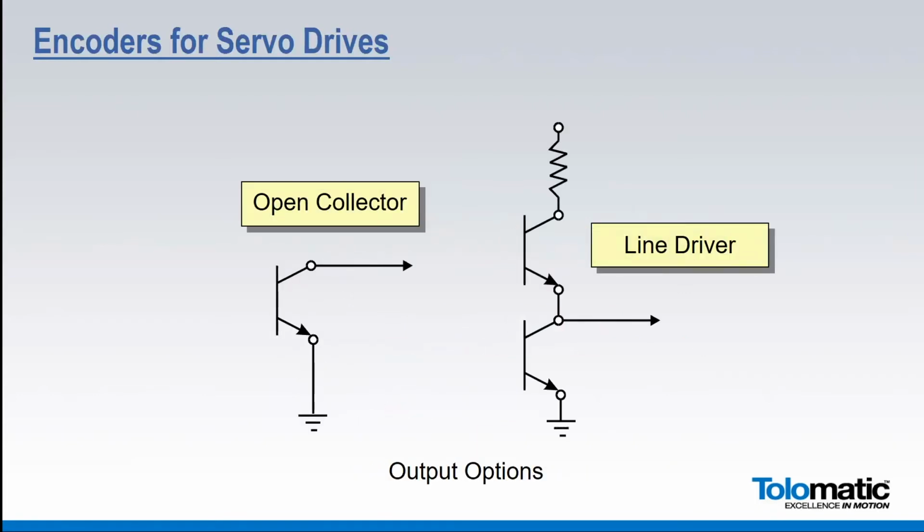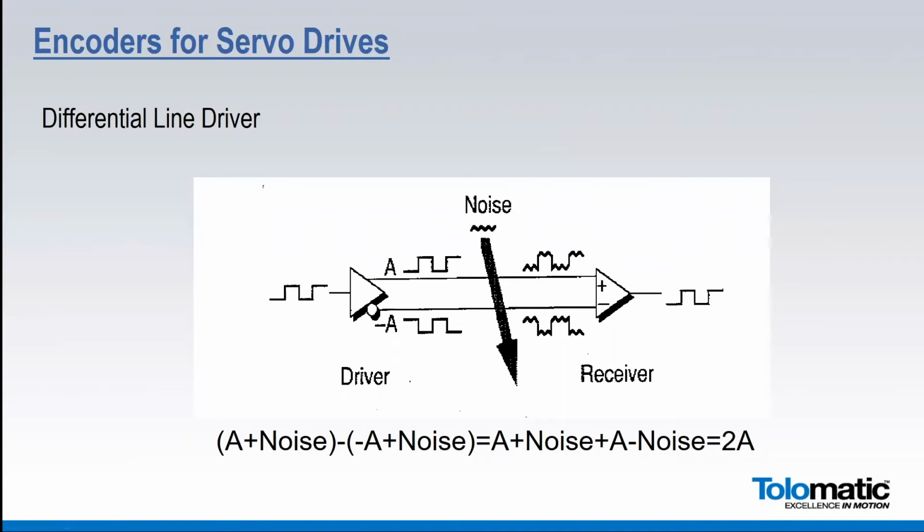Then the other thing with encoders is you have a choice of output types. The basic choice is between line driver outputs and open collector outputs. Typically, if you can, you should use line driver outputs because they drive the line in a specific state, whether it's high or low. Open collector outputs can have a floating state. So line driver is the preferred choice when you're choosing an encoder, if you have to choose one at all. And then the other thing is you may have seen how they have an A channel and an A naught channel and a B channel and a B naught channel.